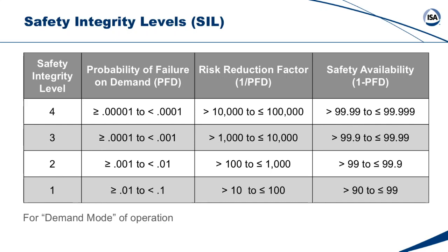But there was one powerful end user in Europe who did get SIL 4 put in the standard, and I don't know anyone other than him or that group, that company, that might have had a SIL 4 requirement. Most people, and the standard's actually very clear now, if you have SIL 4, rethink that. Redesign the process to be inherently safer. I mean, there's no reasonable way to put in instrumentation that you actually think is going to work 9,999 times out of 10,000 demands.